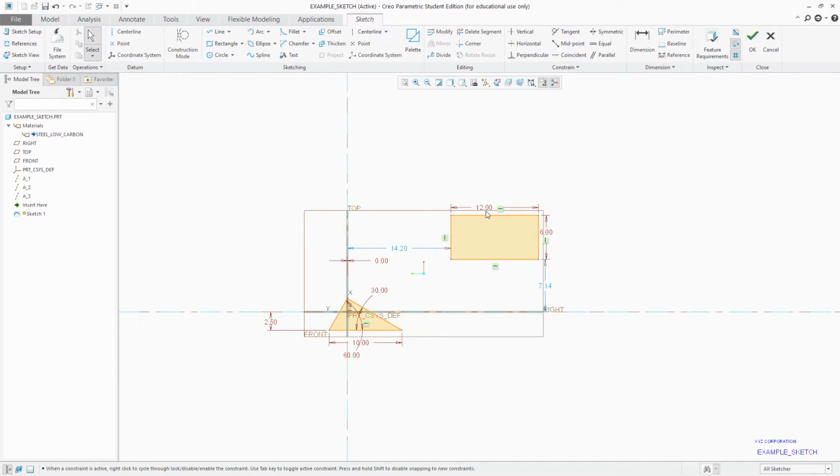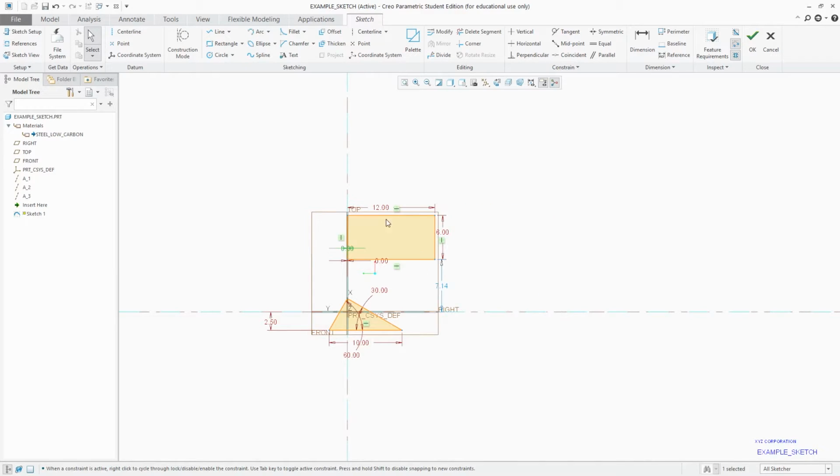Now this kind of rectangle is called corner rectangle. As you can see, I have started it by specifying a corner, then another corner, and now I can locate it with the help of references, like where I want it in my 2D space. Let's make it 0 and this one 5. And now I just want to clear all these entities so that we can see other entities, like how we can create them. And I will also show you how we can delete.